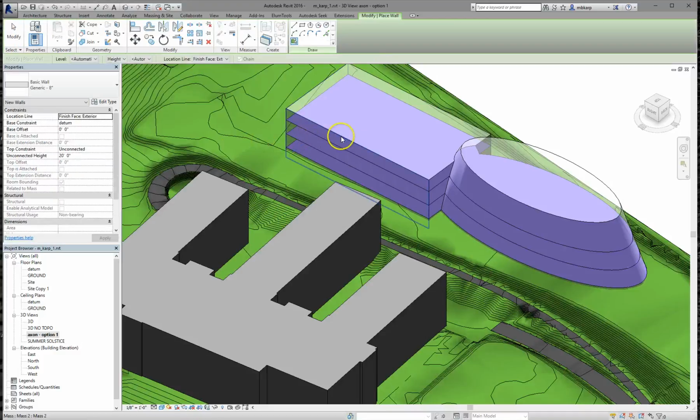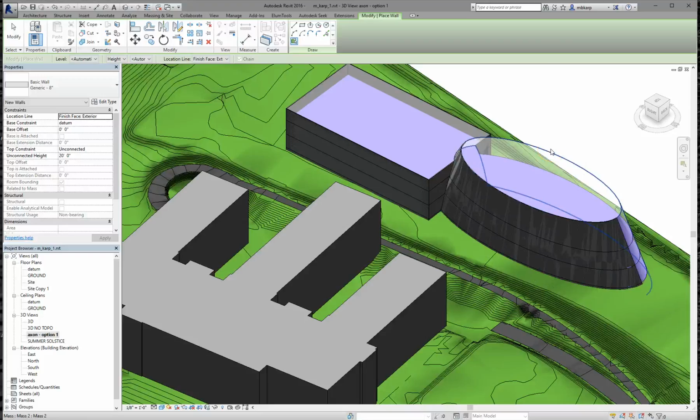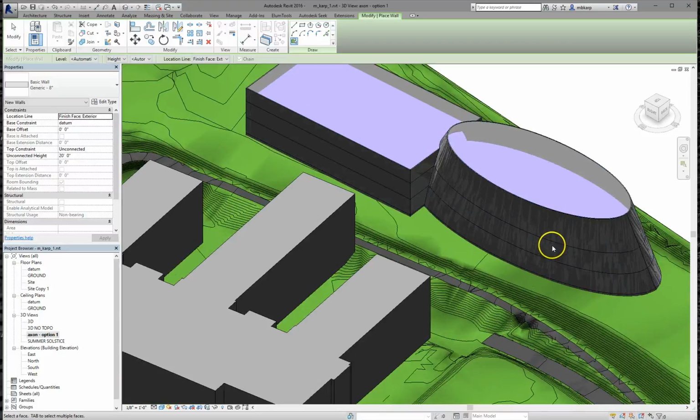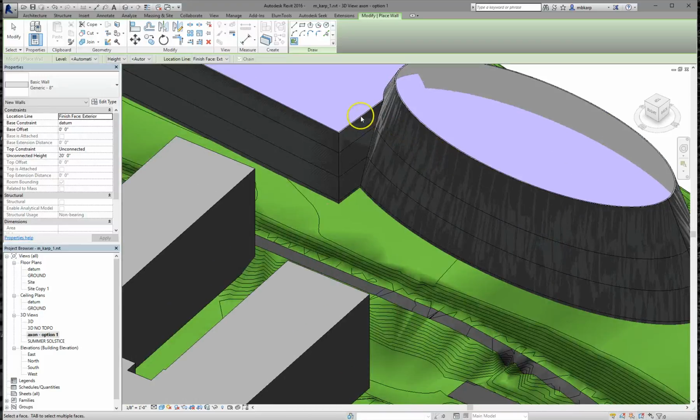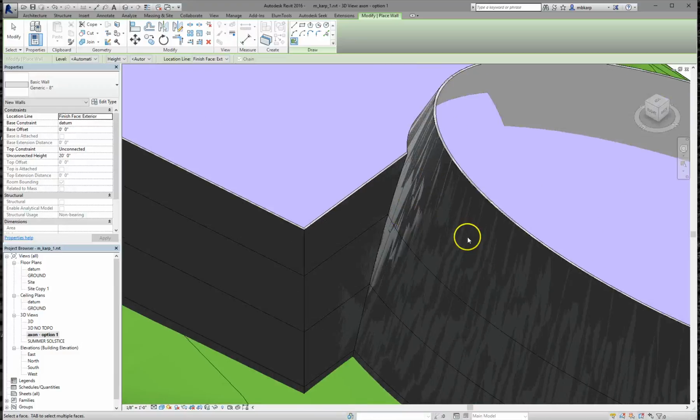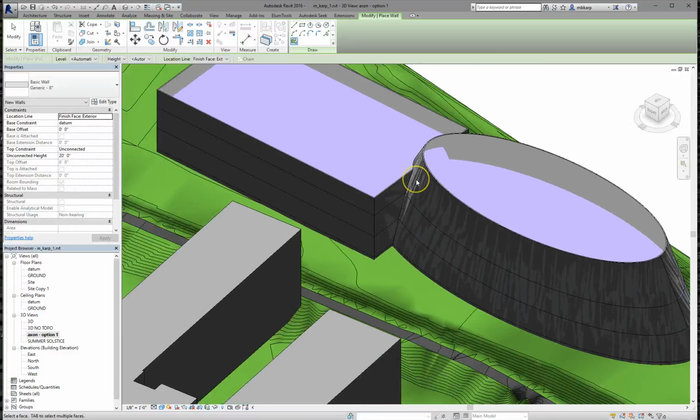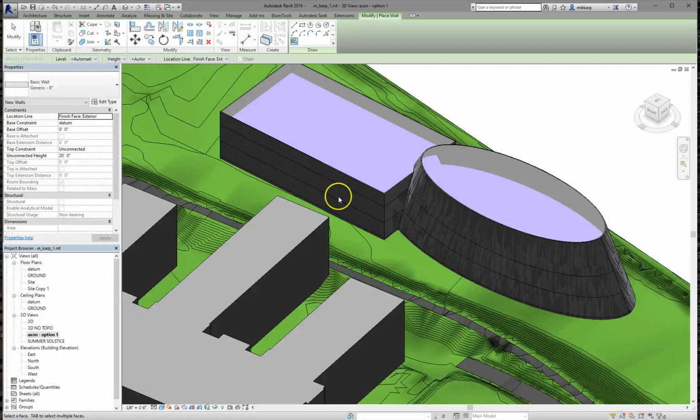So you can see how right now it's trying to select walls. You can see in the type options that this is an 8-inch wall. So whenever I click, I am making an 8-inch wall. Oh, that one's tricky, right wherever this mass is. If I zoom in, since these two are layered right on top of each other, it's giving you a little pattern where the overlapping is happening. But those are actual walls now.